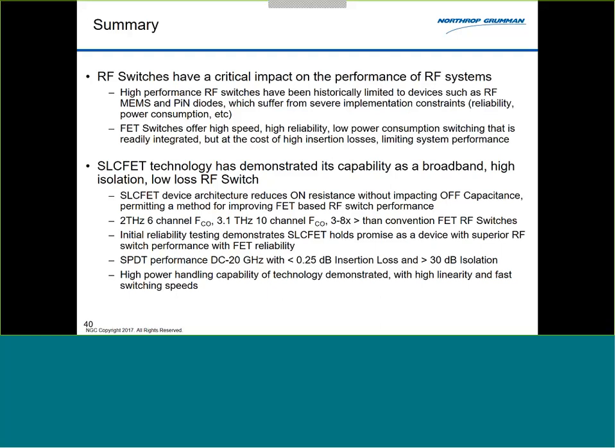But in all cases, for example, that SPDT that I showed in those results can conduct around 6 watts of power, but the switch periphery itself is only 600 microns total W. So it's 600 microns, and then it's an L of 0.25, quarter micron. So in terms of that total area, you're looking at just 150 square microns of material.